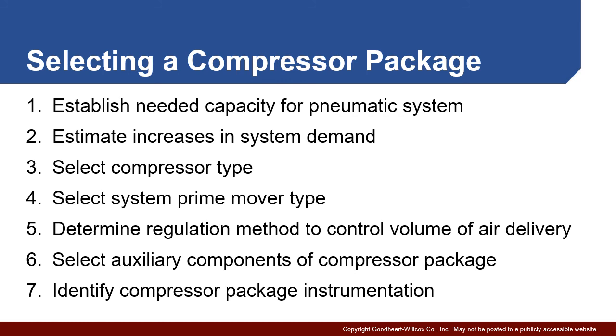You then want to look at which compressor type you're going to use. As I said, by far the most common type is the reciprocating piston arrangement. But if you have very large flows and you potentially want to use a turbine, you might want to talk about the axial flow ones. Or if you're looking for a particularly smooth flow, you might want to use the screw type. So there's some options there.